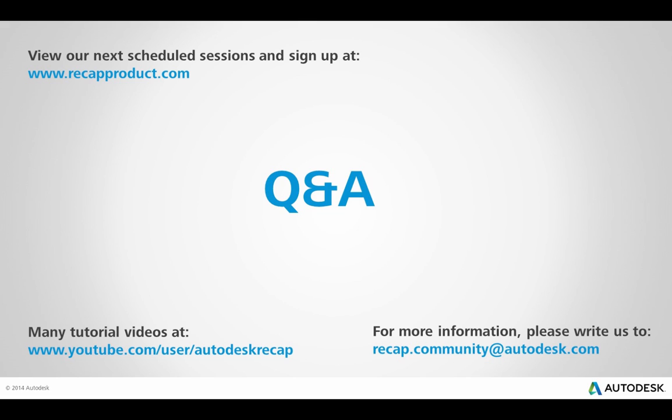Sure, great question. Because we're dealing with a lot of data, millions, if not billions of points, these file sizes can be pretty big, and there's a lot of factors that go into how big these file sizes are. One factor is resolution. Each of these laser scanners has resolution settings on the scanners themselves, so you can set it at a low resolution, a high resolution, a very, very high resolution, and that's going to impact the size of your laser scan files.